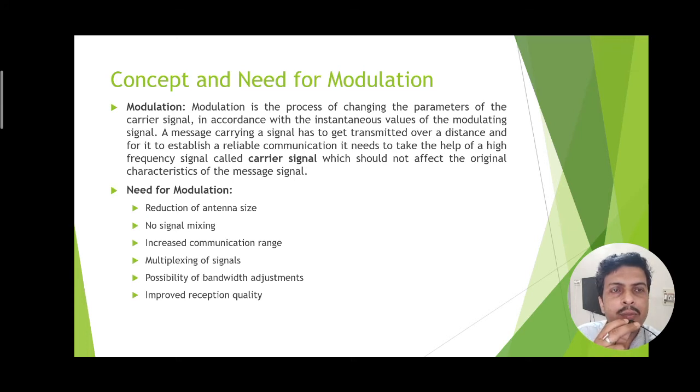The concept and need for modulation is an important fact before going deep into the modulation system. Now what is modulation? Modulation is a process by which a low frequency message signal, that means whatever is the physical parametric variation that has been converted into electrical equivalent signal by means of transducer. So transducer produces the signal which is low frequency as well as low power signal. Now, these signals are not sufficient to transmit over a long distance through the communication medium, such as the coaxial cable, twisted pair line, or wireless communication or optical fiber communication.